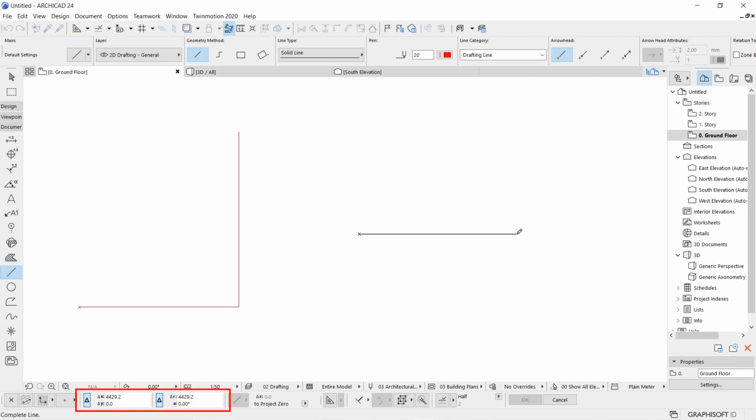And again, it's a very common platform. But if you are a first time user for any kind of CAD software, remember that polar data is nothing but, from the pick point, you define the distance and direction to complete that vector. Because a vector is nothing but a combination of distance and direction. So in this polar data entry format, the distance is always whatever you want to travel, and direction is represented in terms of angle.